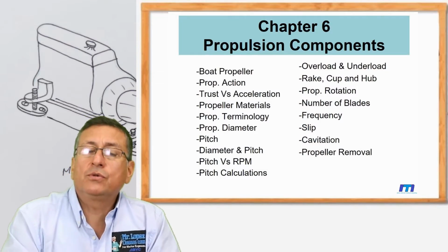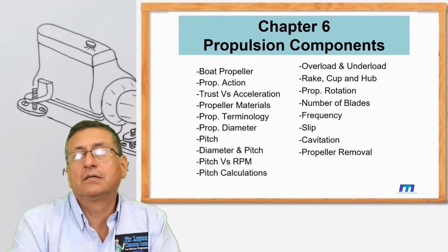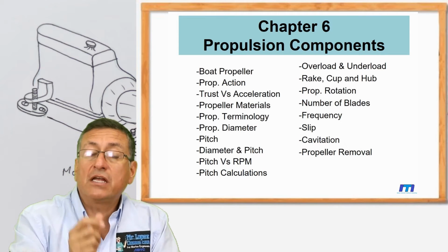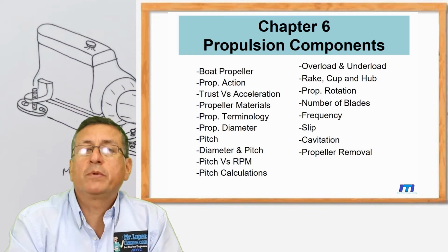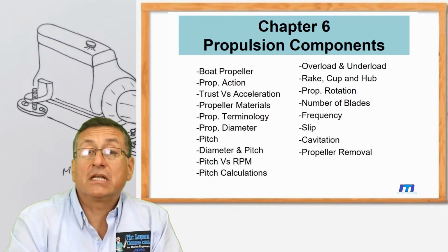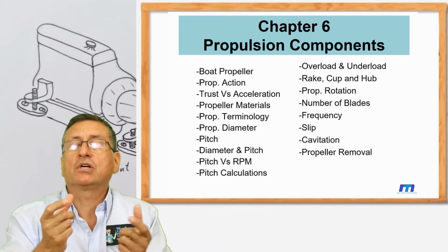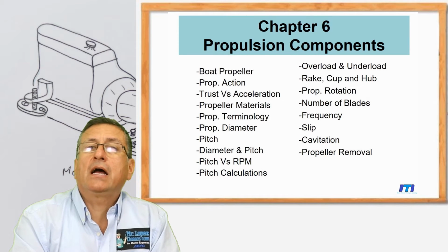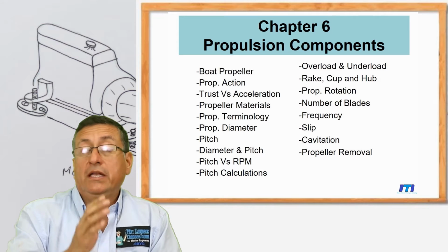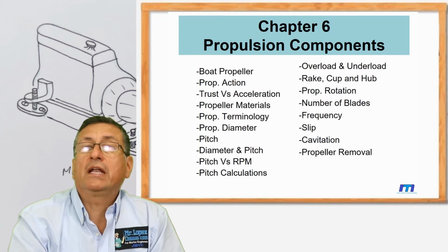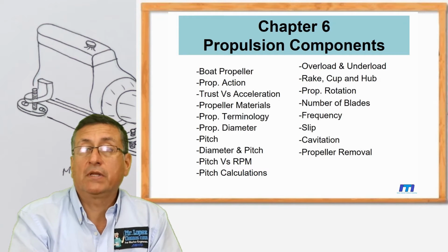And now we are going to check the strut, the bearings located inside of the strut. The name of those bearings are cutlass bearings. We are going to check the procedure to remove those cutlass bearings, and after that we are going to, in the next coming episode, analyze the procedure to align the system.